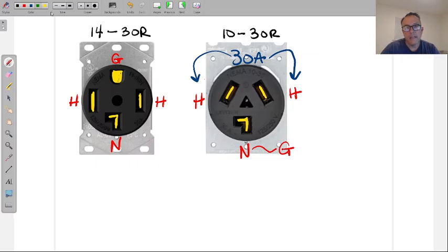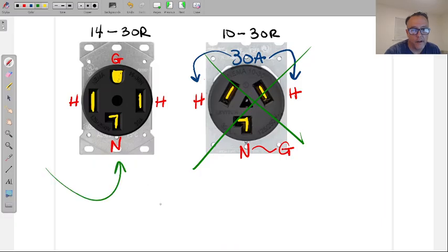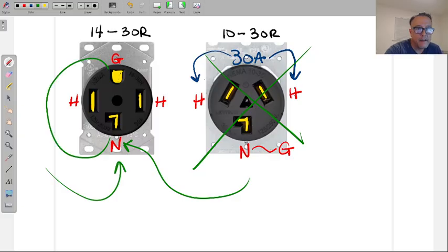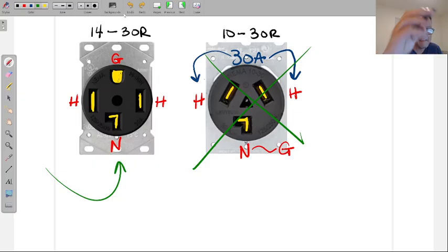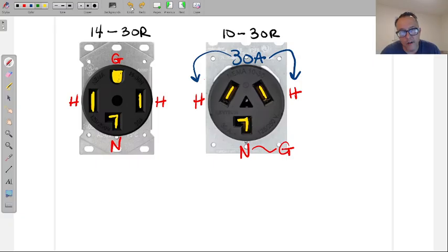You are allowed. The reason why I'm telling you is because if you run into this situation, I don't want you to panic. What is illegal? The illegal part is removing the old receptacle and putting in the new one, and saying, well, Mr. Perez said this was a neutral, and also was the ground, so I'm just going to put a little jumper between here and here. This is highly illegal. I got it on video, which I'm saying. This is no good. This is illegal. Do not do that. We are allowed to still use the old system.